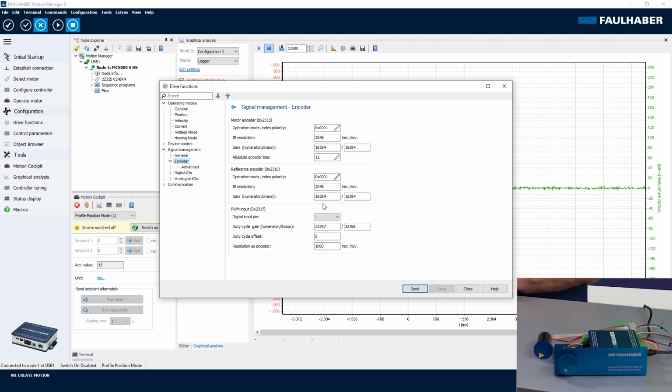Here, in that case, my dial is having an incremental encoder having 512 lines per revolution. This would give me 2048 increments per single turn of my dial. And depending on how I want to move my motor in the demo unit, I have to rescale here. And the idea is always the same. So divide by the number of pulses that you get from the external source and multiply with the number of increments that you want your motor to move.